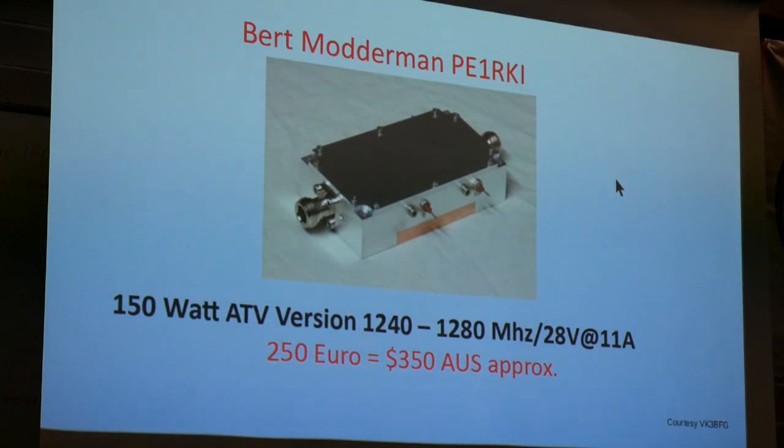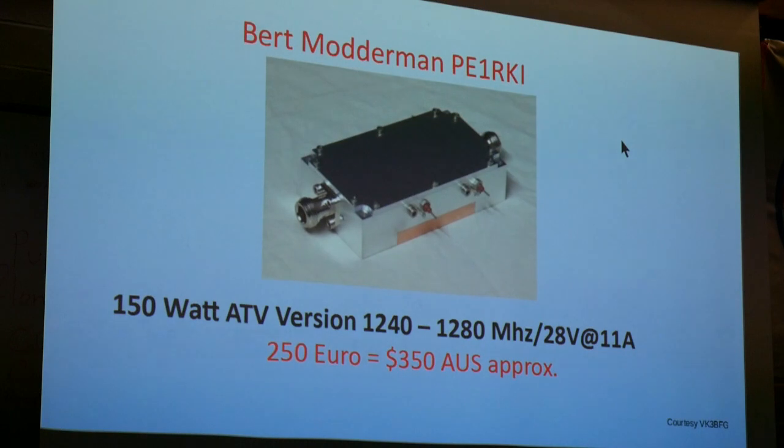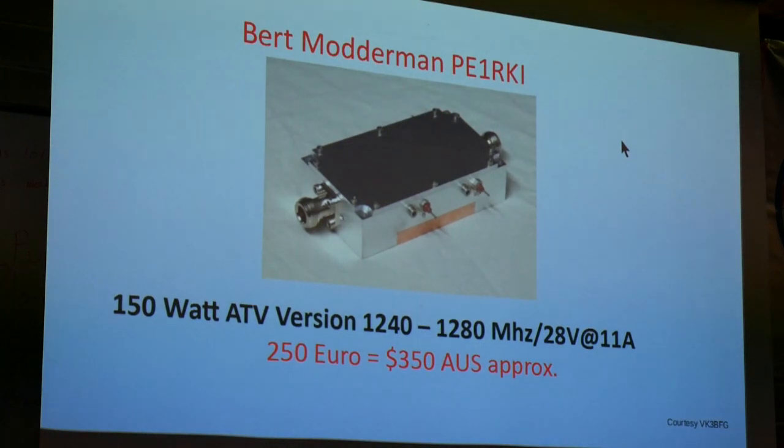If it gets much worse than that, you're not actually winning anything, because you'll think, oh, I'm sending more power, but no, what's happening? You're distorting the constellation. Those points are moving around, they're not where they're supposed to be, and if they go too far, you're corrupting the signal, and there's no point, you're just wasting your time. So you've got to keep it linear and keep an eye on the spectrum analyzer.